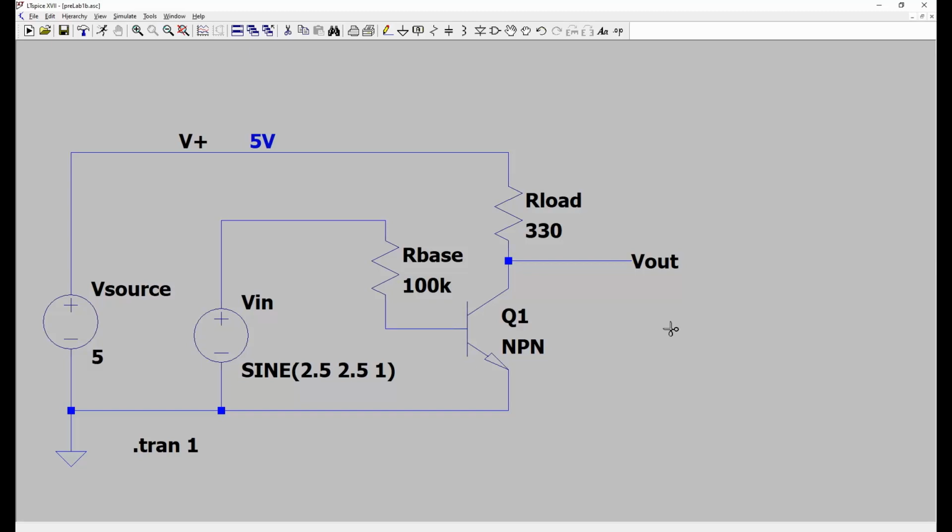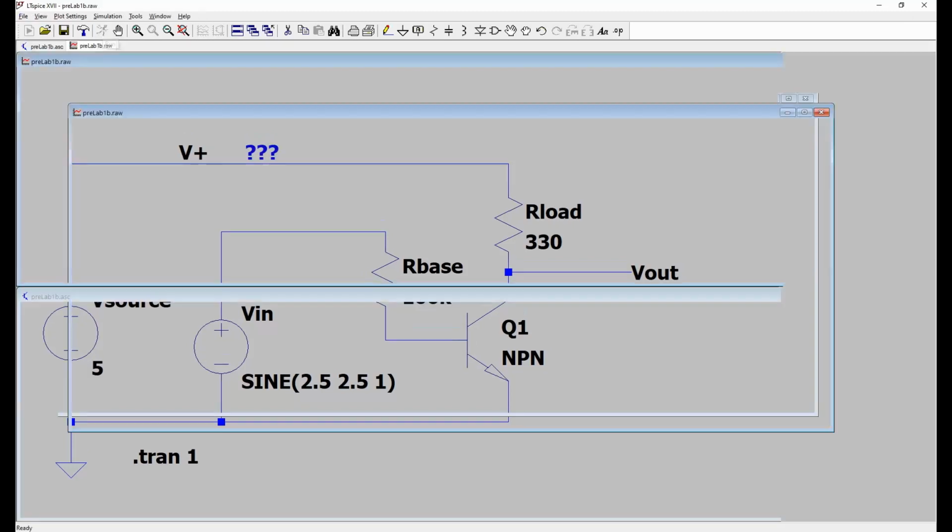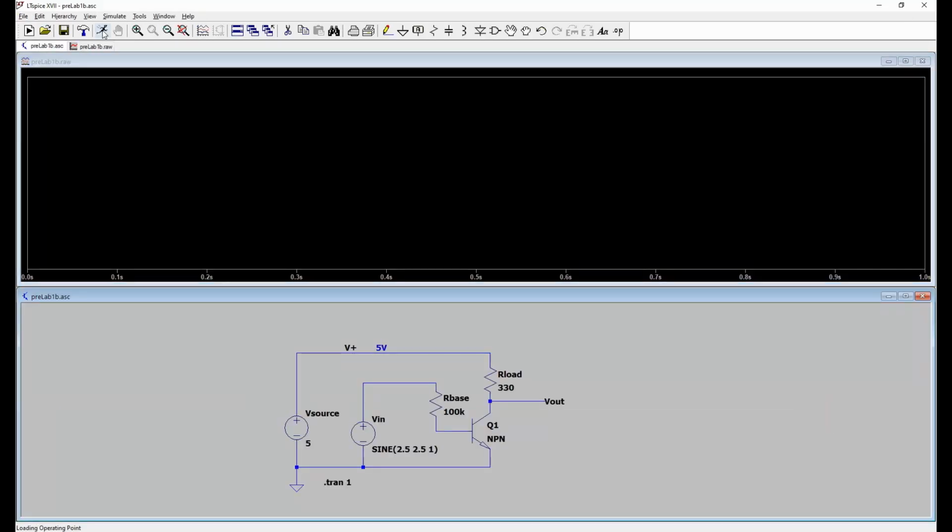So when you first do the transient analysis, when you press run, you're going to get an empty chart until you click something that is interesting, like the voltage. Now, when you see this red probe, it's a voltage. When you see this, it's measuring current. You can read the current on any component, and you can read the voltage at any point.